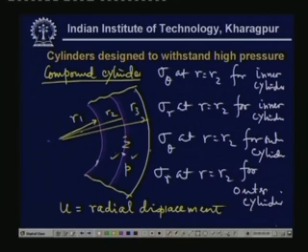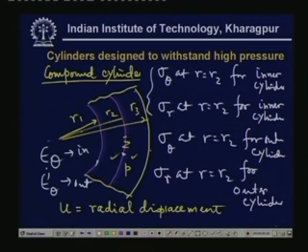So these are to be calculated, and then we will have to calculate the strains epsilon theta and epsilon theta dash, that is for the inner cylinder and for the outer cylinder. From these data we can calculate epsilon theta at the inner cylinder and epsilon theta dash at the outer cylinder, all at r equal to r2. Then once epsilon theta and epsilon theta prime are known, we know u and u prime, that is the displacement of any point. When we consider the point to lie on the first cylinder, let us call this u1, and when it lies on the second cylinder, we call it u2. So it is possible to calculate u1 and u2 knowing epsilon theta and epsilon theta prime, and once we calculate that, then